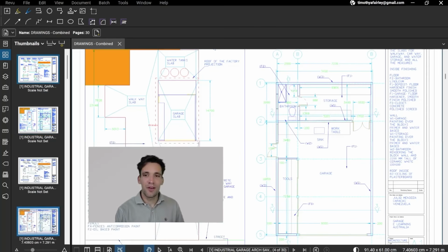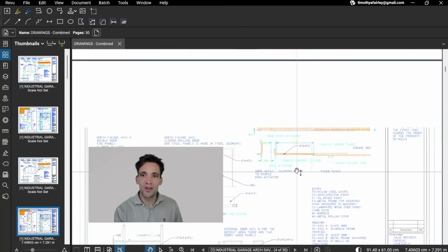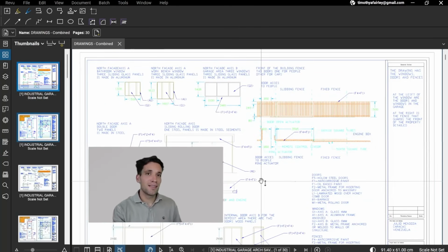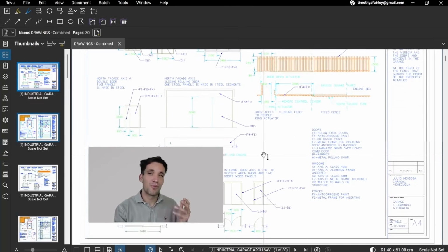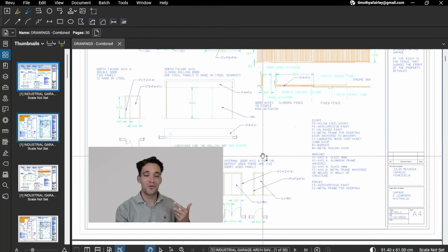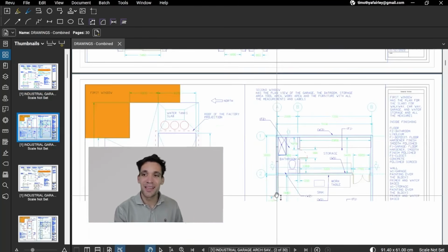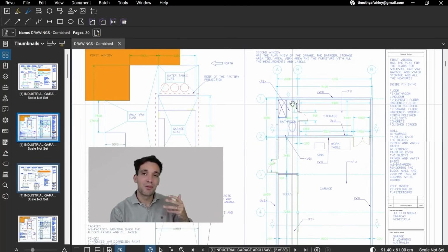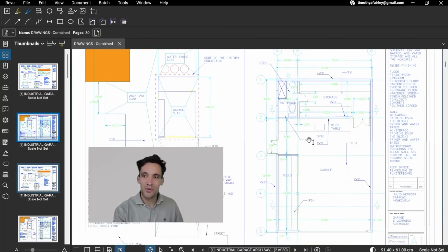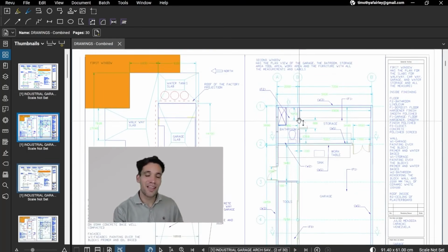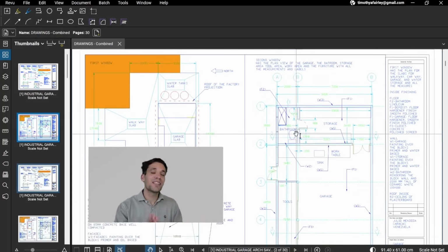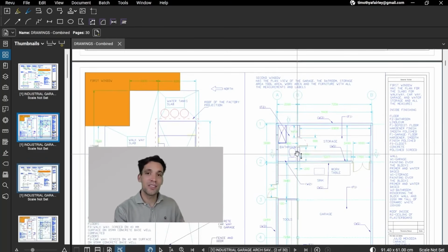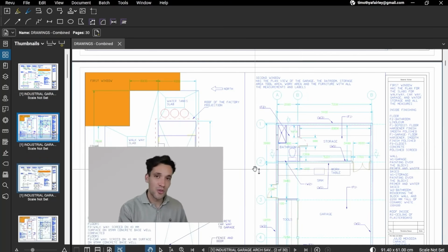Now, something that's tough about building and architectural quantity takeoffs is there are so many different drawings. You'll often see the same structure or wall from 3 or 4 different angles. So one of the actual challenges of doing a building takeoff is not double counting things. For example, if you see a bathroom, there will be a plan view of it, there will be a section view of it, there will be an elevation view of it, and they're all sort of showing the same thing. So you have to be careful with how you go through each of the different types of drawings and when to measure your quantities and when to reference the other drawings for supporting information.